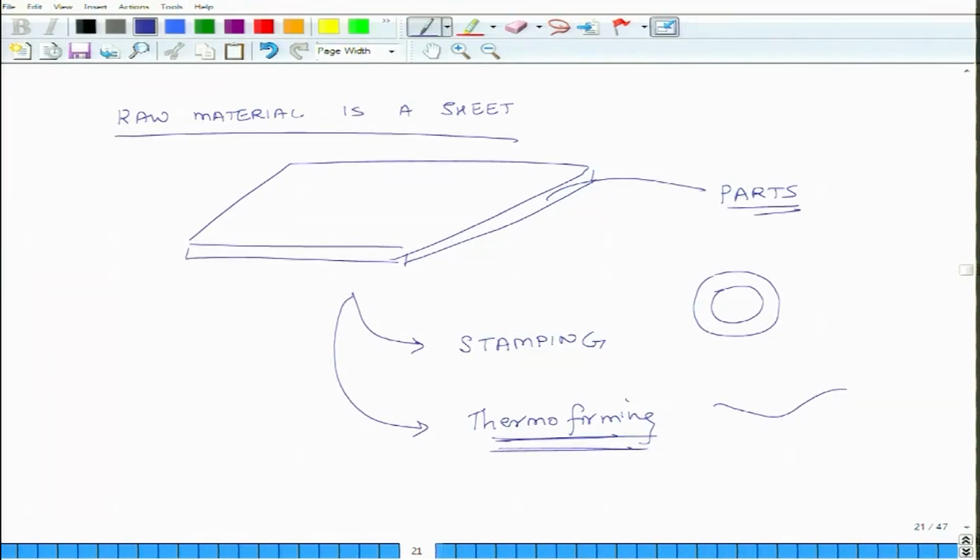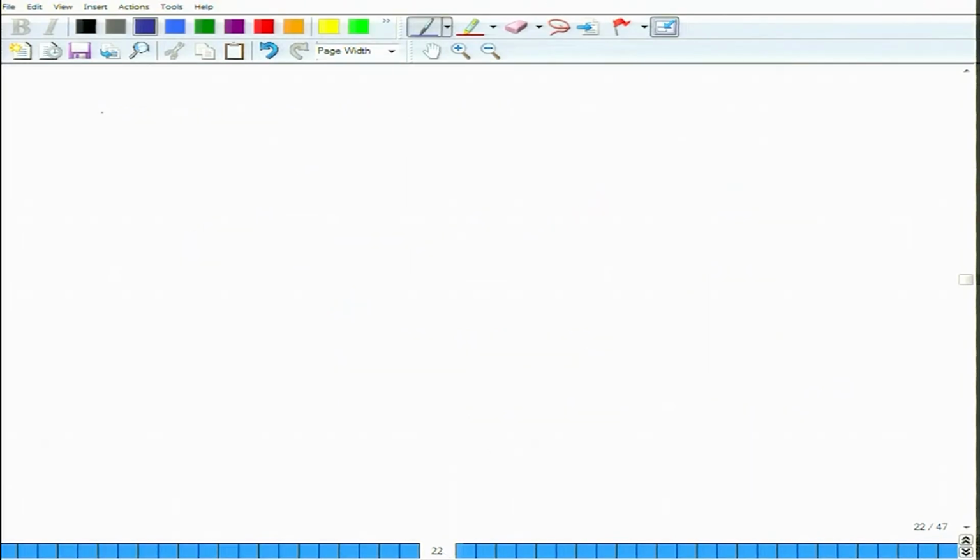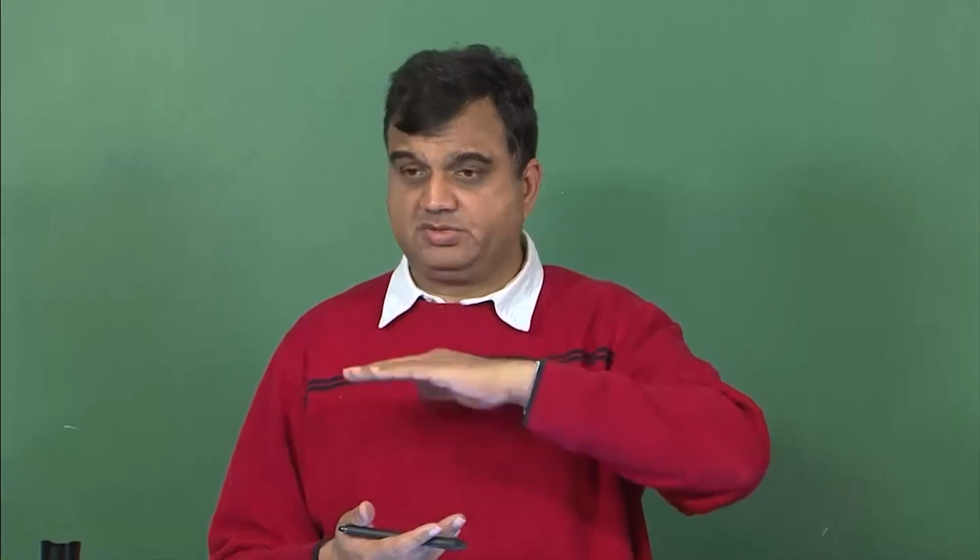And the third process associated with thermoplastic matrix composites is where we have long and continuous fibers, and in this case we may have sheets with fibers of specific orientations, and these could be thin sheets.